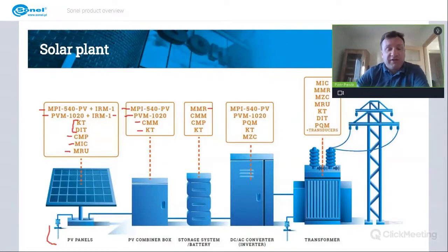We can check the continuity of a battery string, and we can check voltage and current using the multimeters and clamp multimeters, and make sure that nothing is overheating with thermal imagers of KT series. Because of course, if we have a faulty battery, we should be able to see that it is overheating.